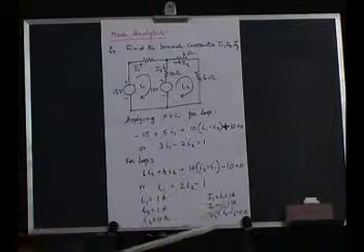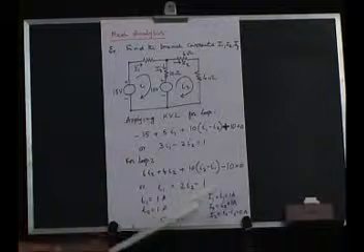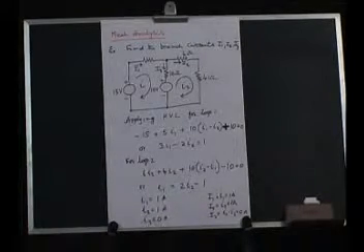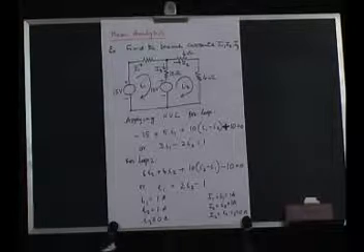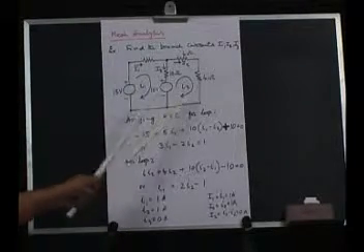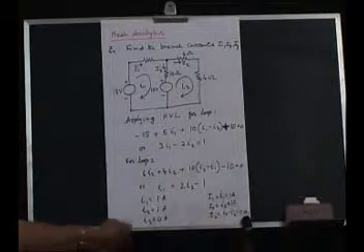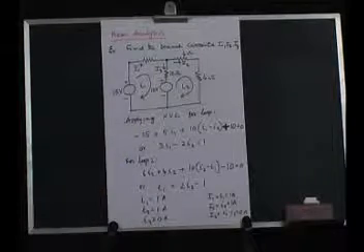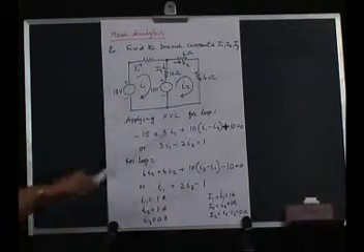I2 is also like that. I2 is the loop current and the branch current is one and the same. We have 1 ampere. What about I3? For I3 we have the equation: I3 is I1 minus I2. Therefore, I1 is 1 ampere, I2 is also 1 ampere, so no current flows in this. So this is the solution. If we get I1 and I2, we have everything.